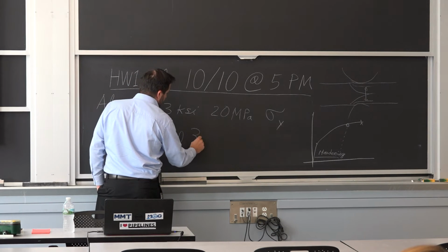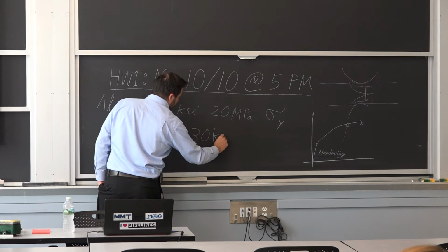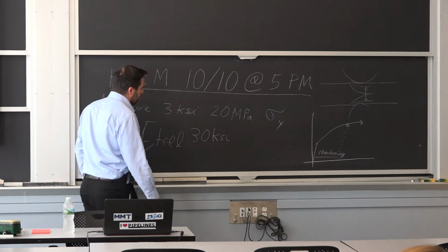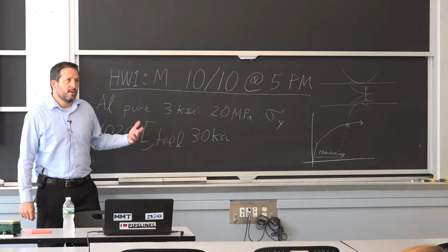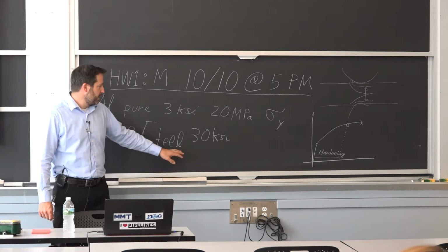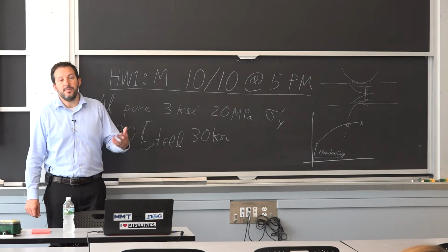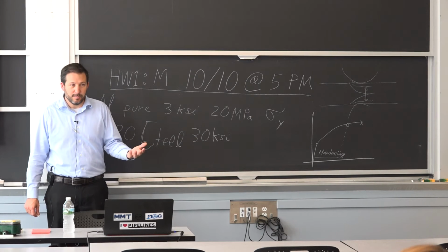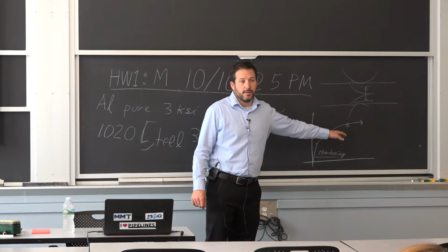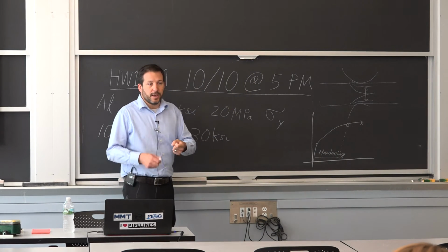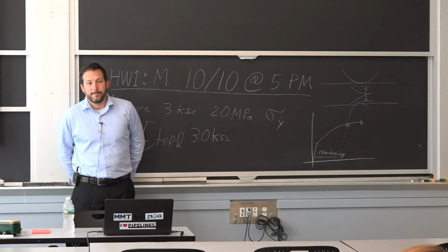You can't really get it much lower than that. And when I mentioned a factor of 3 here for the aluminum, for steel, well, it's almost a factor of 5. So you can get these to be 150 KSI with almost the same composition by cold hardening it and having this very big texture that raises your yield strength.